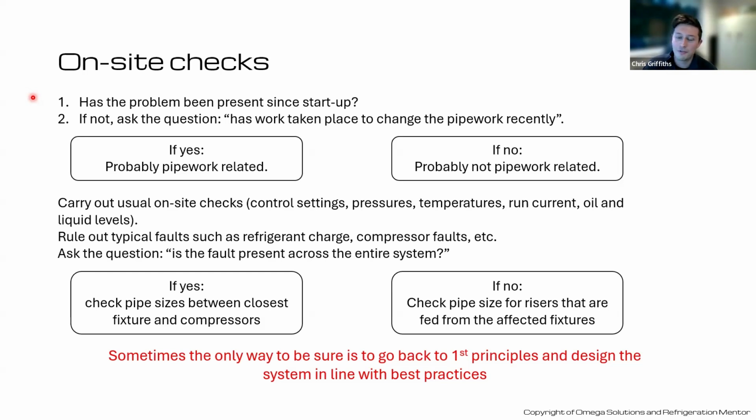Yeah, so it's worth knowing about the refrigerant. Again, Danfoss is really helpful for this with their app, I think it's called Ref Tools. Excellent. It has a refrigerant slider, a comparator for any refrigerant you're realistically going to use out there. So you can bookmark some of the preferred refrigerants if you work with them on a daily basis. I think I've still got 134A and 404 on there from whenever I came off the tools, 7 or 8 years ago. I don't think there's probably a 404A system out there to work on nowadays. Well, hopefully not anyway. There's less and less of them.